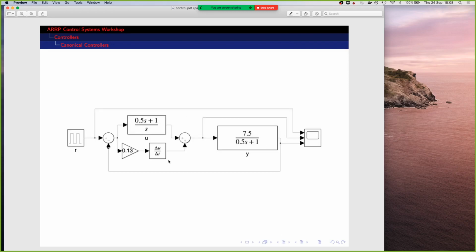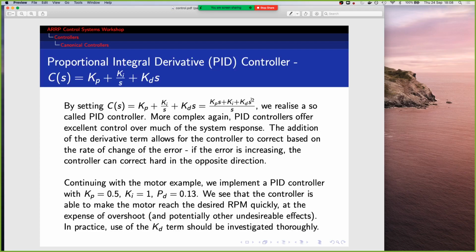So here's a... Yep. Why is it the form that it is? It's an S squared over S kind of form. So this term here just comes from putting this in a fractional form together. Yeah. So if you multiply through by S on S to normalize that fraction, it'll come out to be this. So this is the term that we typically like to visualize, but oftentimes you can analyze a transfer function much easier if it's in a rational polynomial form like this.